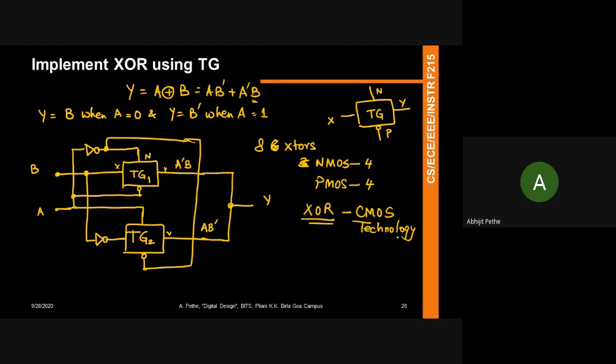So in special cases, again, you see that the transmission gate cannot be general. I mean, you can generally apply it to design, but it may not be advantageous. It becomes advantageous in certain special cases. For example, in this case, when you're doing an XOR gate, it becomes advantageous to design something this way. Okay. So with this, we will close combinatorial circuits. We will close digital logic families. So starting Wednesday, we'll start my favorite part of the course, which is sequential design. Okay. So now we'll introduce clock. We'll start now thinking how best to reuse hardware.